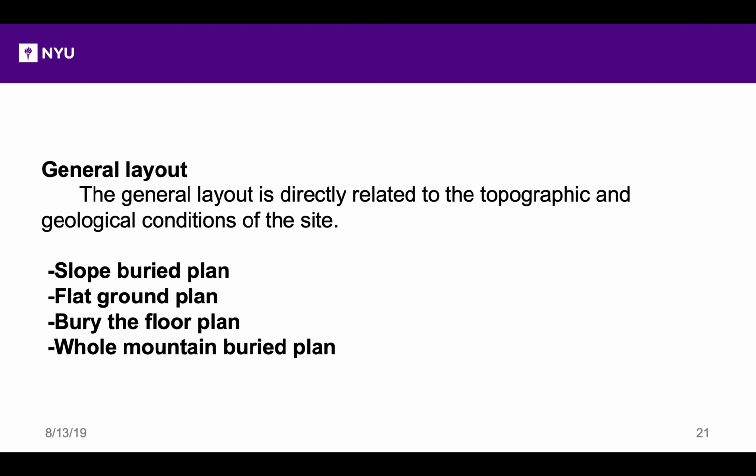The level earth barrier plan: the underground workshop is arranged in the mountain. The ground workshop is arranged on the platform outside the slope, and the underground workshop and the ground workshop are arranged on the same elevation. Above the reactor building cavity, a construction yard is laid out on the platform, with a hoisting shaft connected to the surface on top of the reactor building cavity. It is used for construction within the reactor building containment, structural and related equipment hoisting, and transportation. After the nuclear power plant starts operating, it is closed using concrete backfill, and on the construction platform a pool, high building, fire pump room, and so on are arranged.